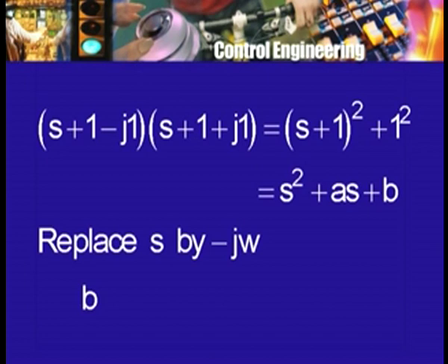So, at the DC end we will again have a constant gain given by this number b, or 20 log to the base 10 of b, or minus 20 log to the base 10 of b, depending on whether we have the numerator, that is 0, or denominator. So, that is taken care of. So, the DC asymptote is going to be a horizontal line.